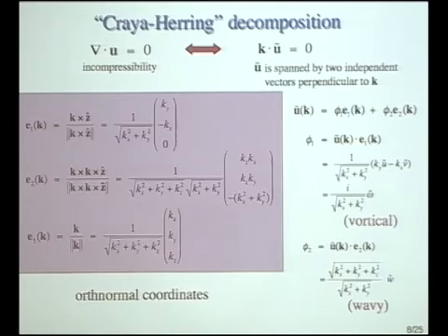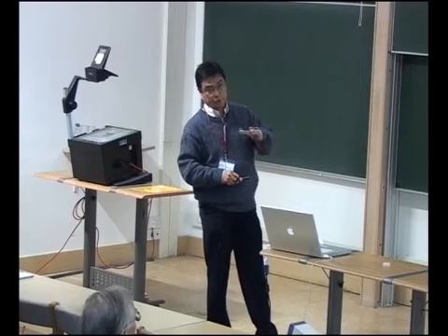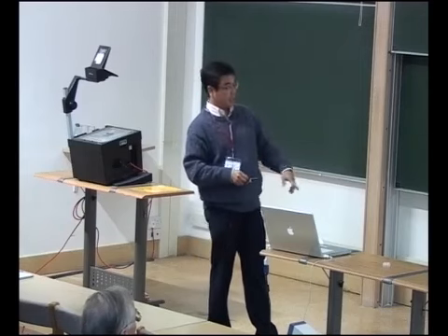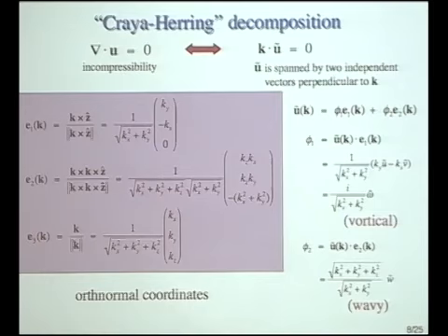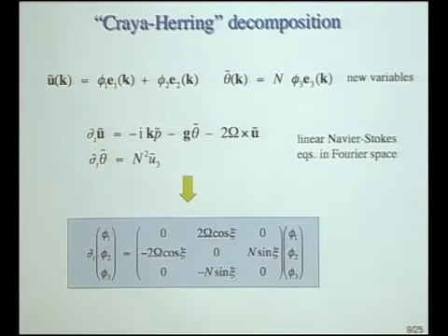So omega z is the third component of vorticity, which is why phi1, the coefficient of the first mode, is called vortical. The second coefficient is calculated in a similar way, and gives w, the third component of velocity. The third component of velocity is coupled with temperature fluctuation and gives the wave features of turbulence, so phi2 is called the wavy component.